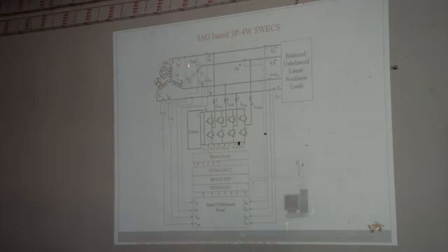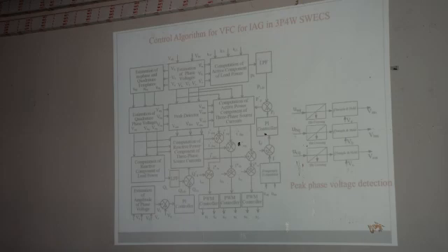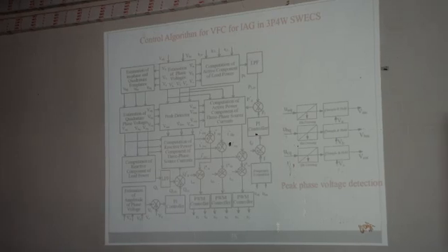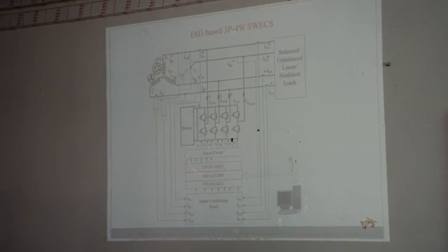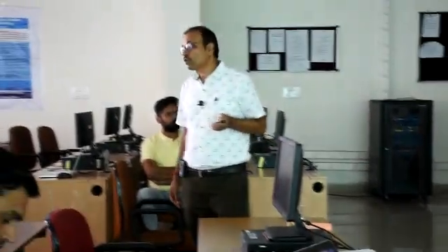So here, this is your induction generator. As I told, only one converter is used, and then it is connected with the loads. So you have a constant voltage, constant frequency operation in the presence of this 4-leg converter, 4-leg DSC, in support with the battery energy storage system. This is the control algorithm used to guide the operation of this 4-leg converter. The 4th leg is used for neutral current compensation because at the load end we don't know whether the load is a 3-phase load or a single-phase load. So your system should be compatible for this.